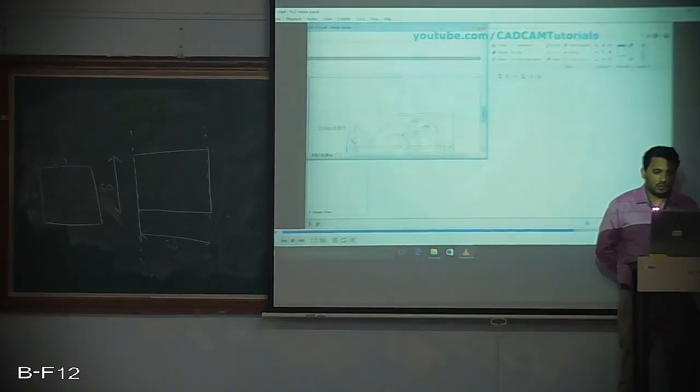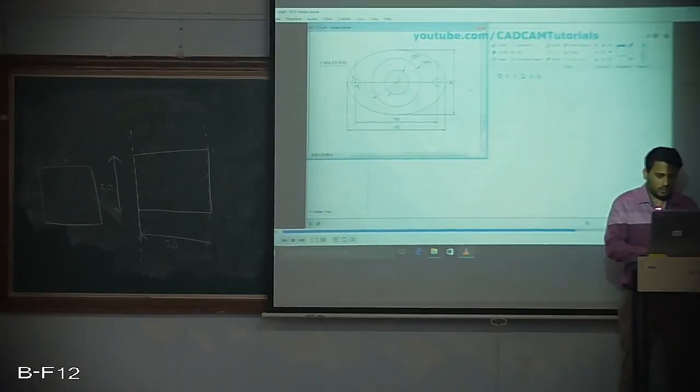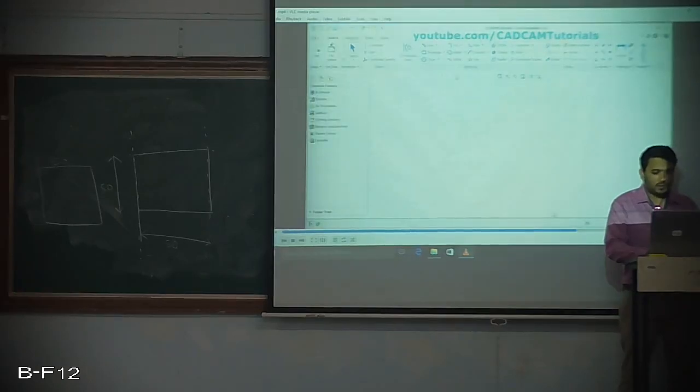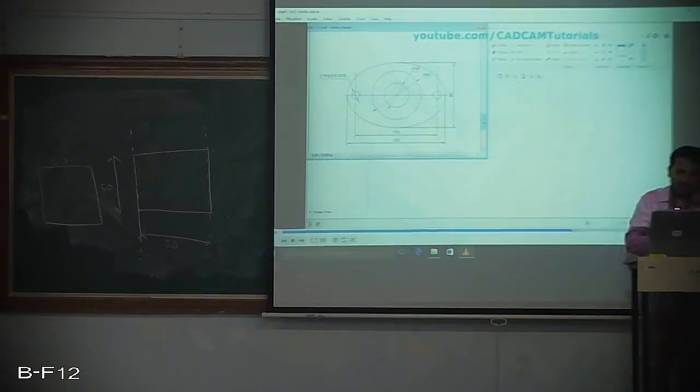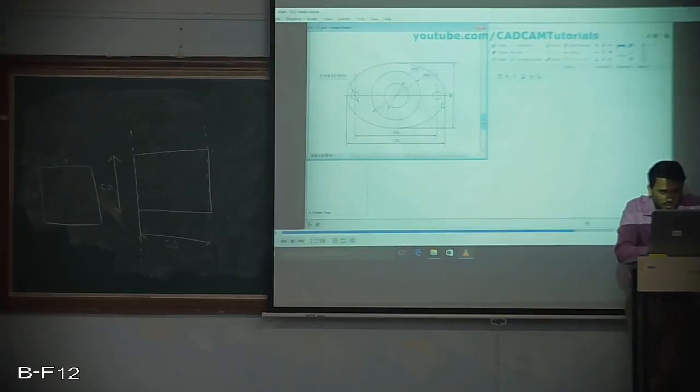Again in the sketch environment. So this drawing. So what is there in this drawing? So here I am going to draw this line. Just draw an ellipse first, and then put a horizontal axis dimension as 100 and vertical axis as 80, and then you can draw an axis line,